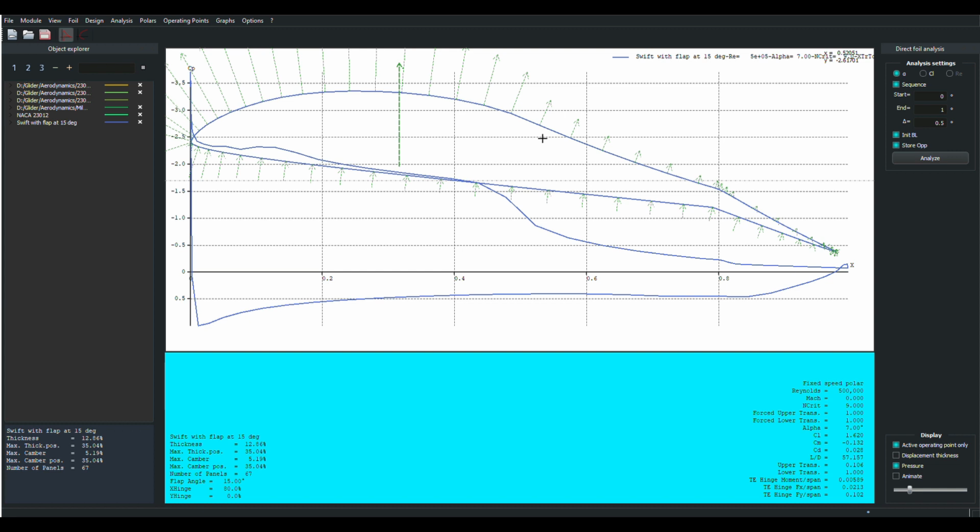And I think, I'm guessing ahead of time because I haven't actually done this yet, but just by happenstance, that's going to come out looking a lot like the elevons I had on my original wing, of all things, because of where it was hinged, how it was hinged, and how the elevon was built. And all of that was done for reasons other than aerodynamics. In fact, at the time that I was doing it, I thought, well, this is kind of crummy on the aerodynamics, but I'm going to eat that trouble, I'll eat the extra drag to get the transportability. But the fact of the matter was I accidentally designed in the right answer unintentionally.